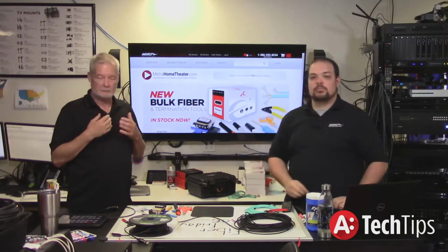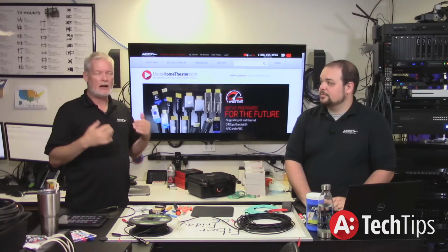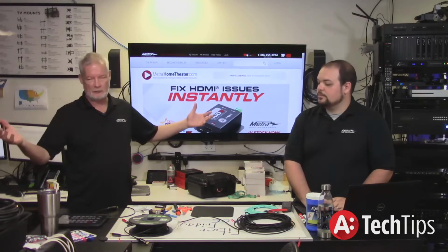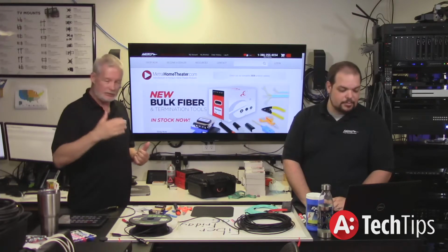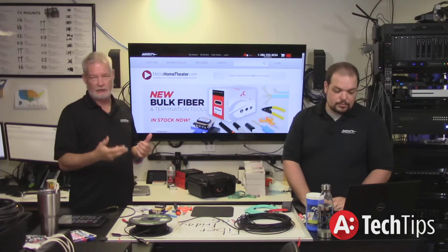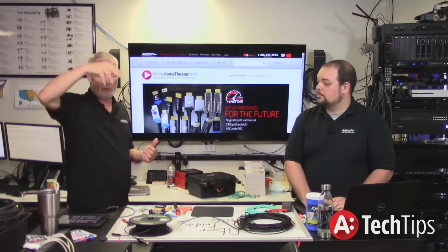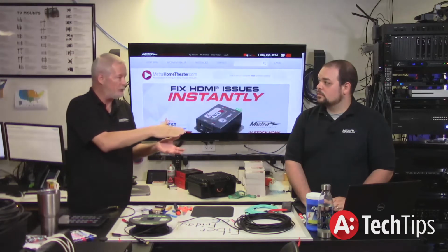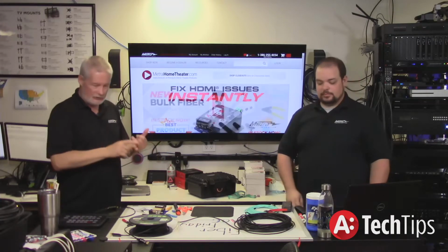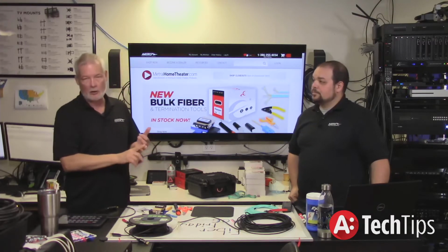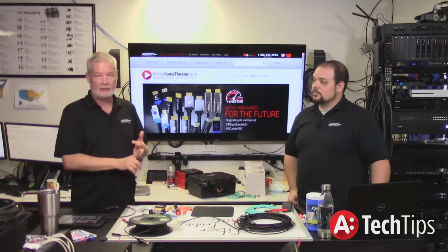My philosophy, my thought process, because we don't know these answers yet, is we're not in a position to legitimately, industry-wide, transmit 48 gig now. We think that what we're going to see is DSC, display stream compression, where they're going to take what could be 48 and cram it down into 24 to 30. Because they're going to have to do this out of the gate, plain and simply. The TVs really are not ready. The hardware is really not ready. The infrastructure to support the content is really not ready.